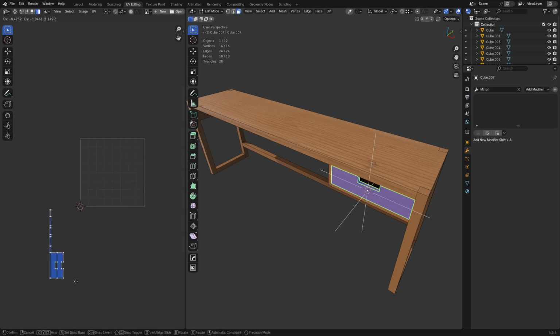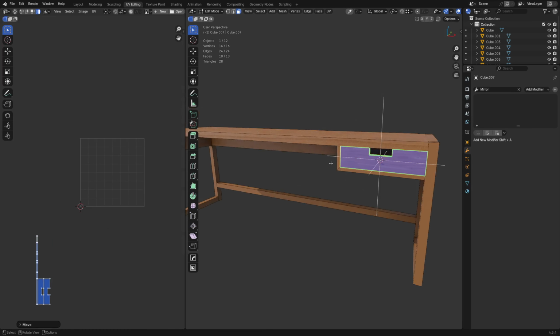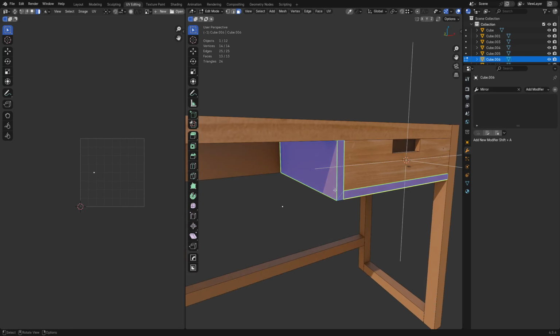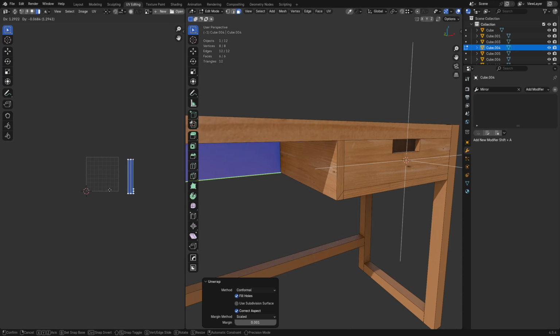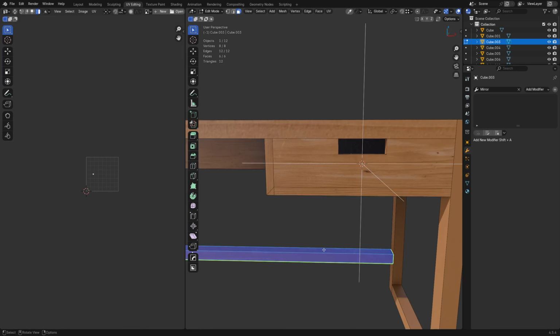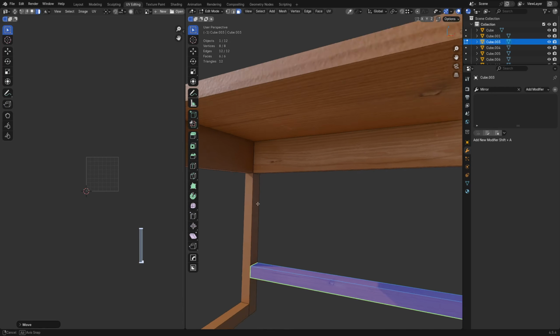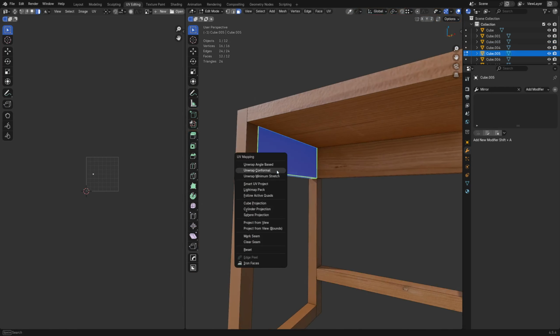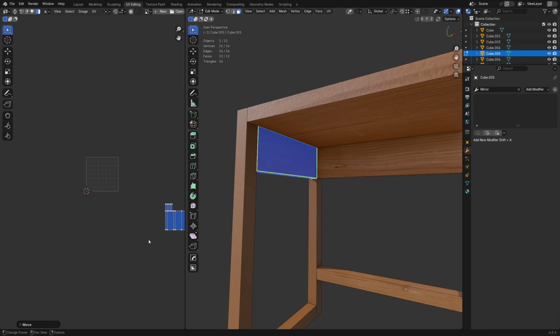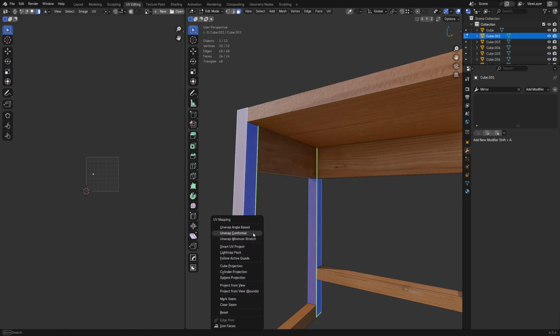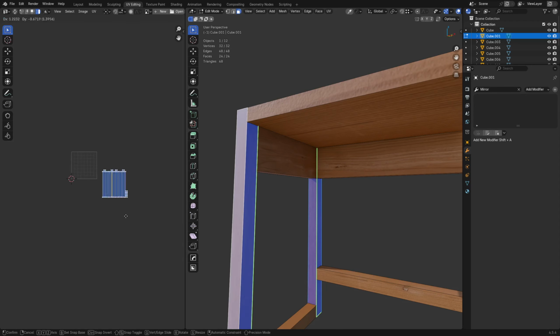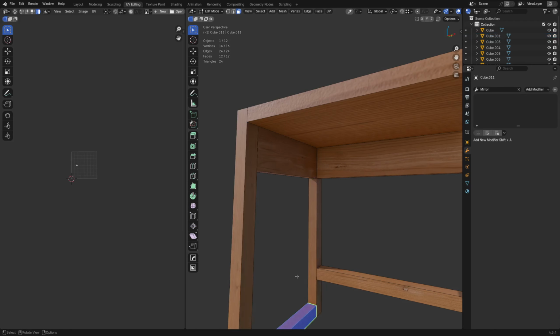You move it somewhere where it doesn't overlap with that one, right? So this was a good practice to get into where you press U, unwrap conformal. And you can just move things around and try to make sure that you don't overlap them. That's the big thing, right? So you want to make sure they're all working. That's more of a proper UV kind of job there, basically. Like when you go through the whole process of working things out. You can do this as you're modeling sometimes, but a lot of times it's better just to do it later.